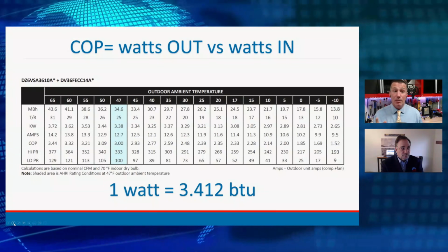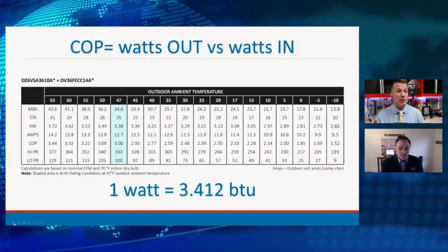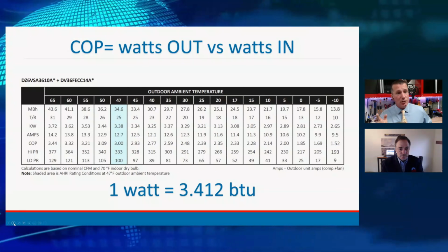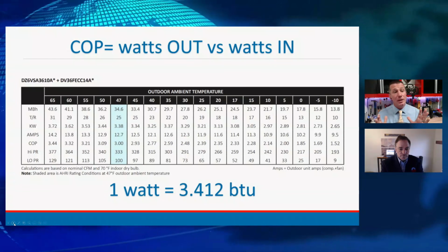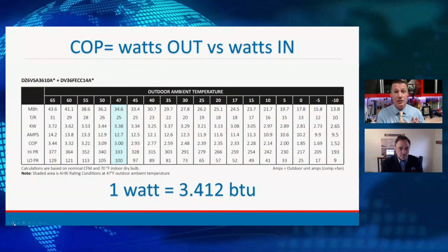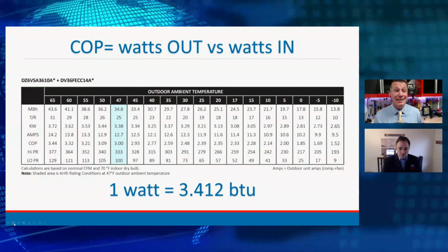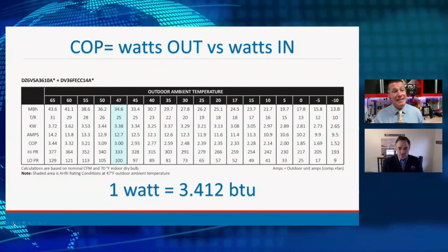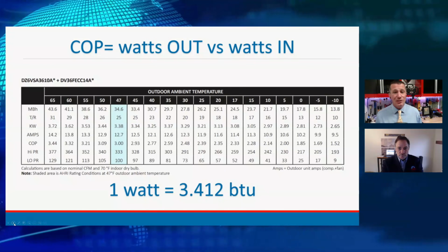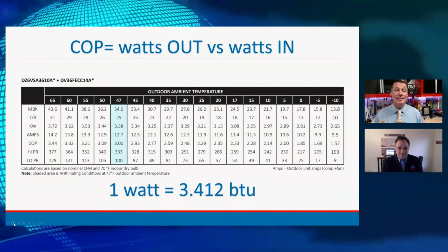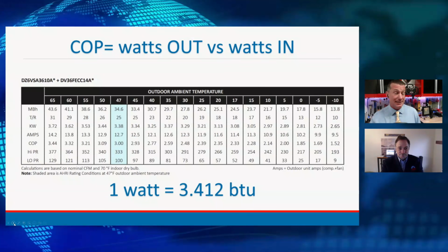So our modern heat pumps are very effective at producing heat, even at lower temperatures. If we look at the lower temperature range on this one, this unit actually goes down to -10. And this is where it's important to read these installation manuals to know how low of an operating condition we can produce with that particular piece of equipment. This one at -10 is still producing 13,800 BTUs per hour, and it's doing it with a coefficient of performance of 1.52. That means it's 52% more efficient than electric resistance heat at -10.